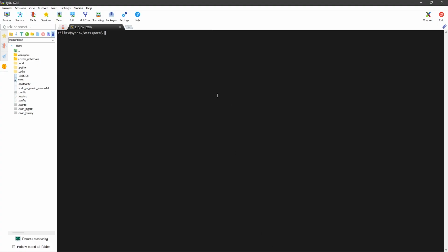Now, let's get into the coding. I will walk you through the step-by-step process to build a web interface for controlling the LED. Here is the console of my FPGA board running Linux. First, make sure you already have the PYNQ overlay files for the GPIO that control the LED. If you haven't done this yet, you can refer to my tutorial on how to create a custom PYNQ overlay. You can find the link in the description.